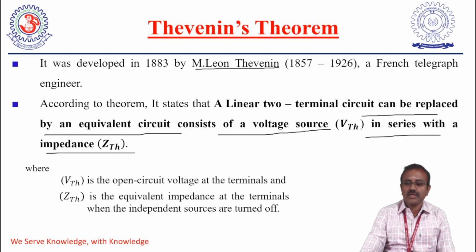What is the meaning of VTH? VTH is nothing but the open circuit voltage at the load terminal. ZTH is nothing but the equivalent impedance at the terminals when the independent sources are turned off.